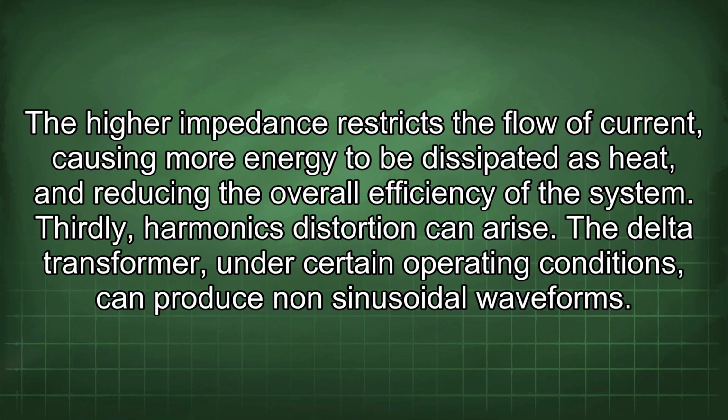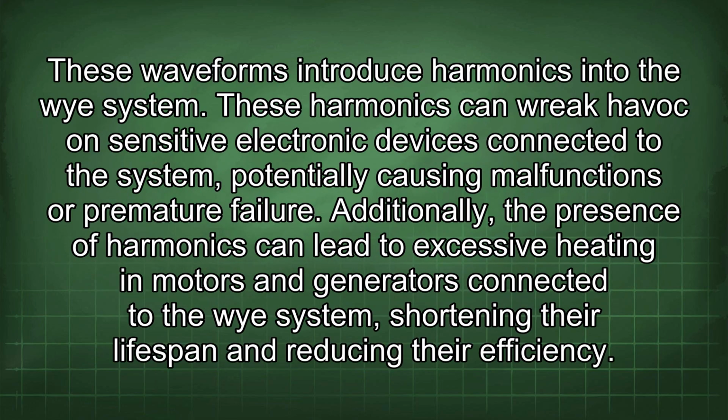Thirdly, harmonics distortion can arise. The delta transformer, under certain operating conditions, can produce non-sinusoidal waveforms. These waveforms introduce harmonics into the Y system. These harmonics can wreak havoc on sensitive electronic devices connected to the system, potentially causing malfunctions or premature failure.